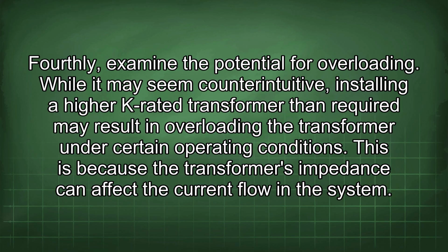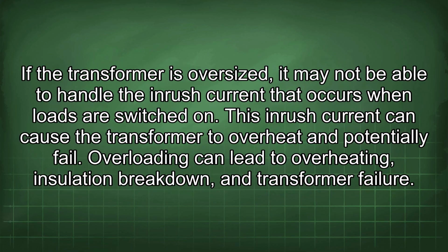Fourthly, examine the potential for overloading. While it may seem counterintuitive, installing a higher K-rated transformer than required may result in overloading the transformer under certain operating conditions. This is because the transformer's impedance can affect the current flow in the system. If the transformer is oversized, it may not be able to handle the inrush current that occurs when loads are switched on.